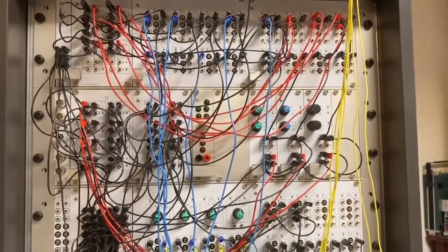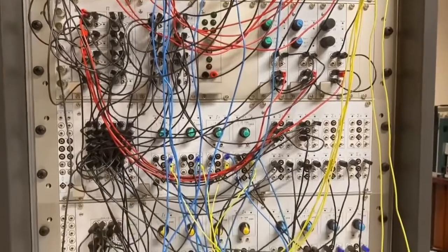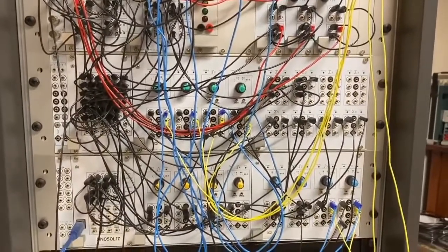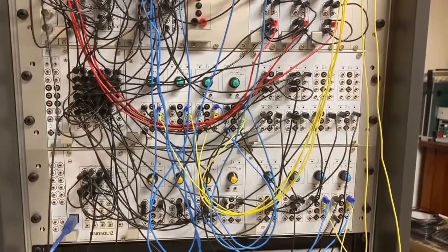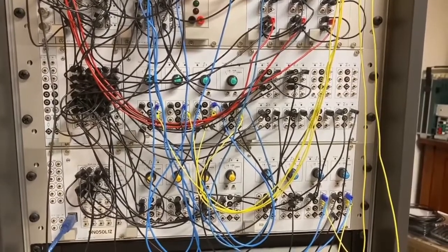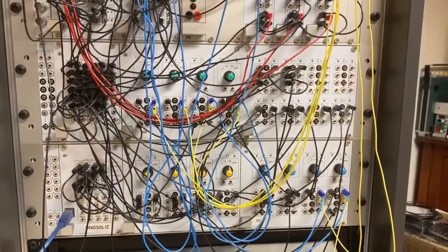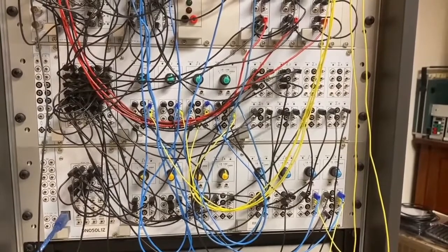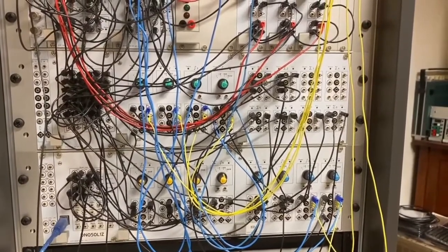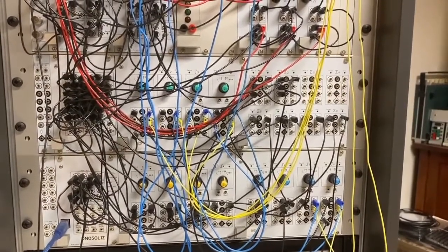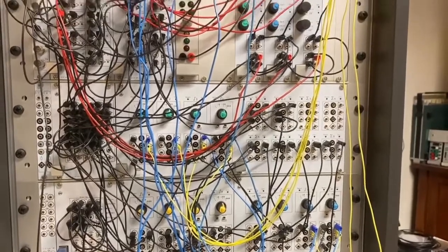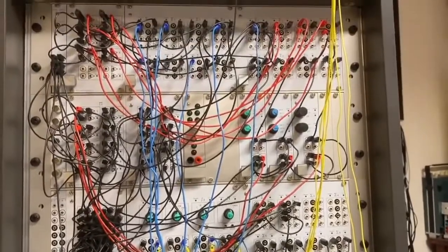So this setup, which currently represents the simulation of a water molecule, has no manual potentiometers at all. All the potentiometers are digitally controlled, and as it's currently set up, you have 32 10-bit potentiometers being controlled by the attached digital computer, and the digital computer can also read out the results of your simulation even in real time and display it on the digital computer, or do some post-processing as required by your particular problem.